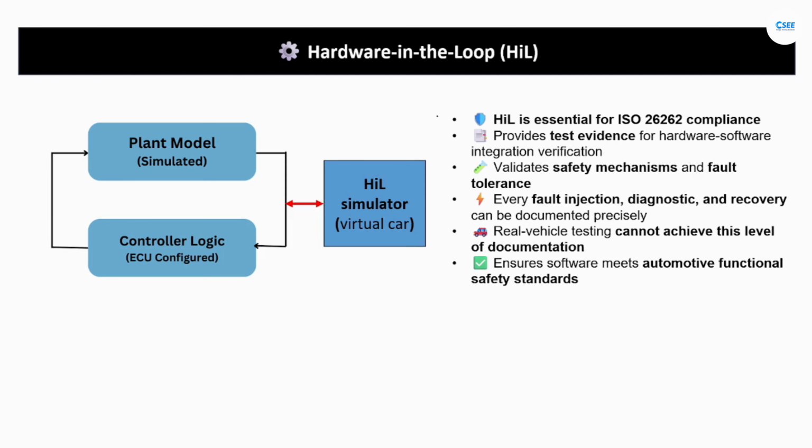And speaking of safety, HiL is absolutely essential for ISO 26262 compliant automotive software. It provides the test evidence for hardware-software integration verification, safety mechanism validation, and fault tolerance checks. Every fault injection, diagnostic behavior, and recovery response can be documented precisely, something not feasible with real vehicle testing.